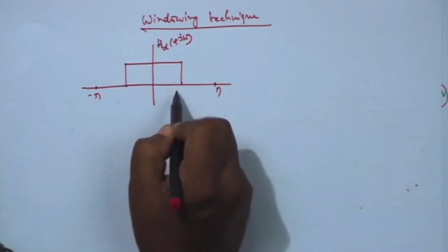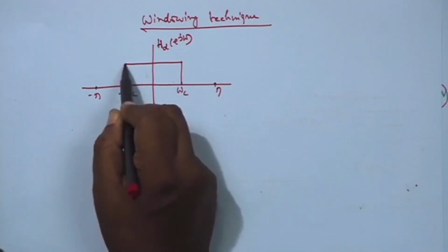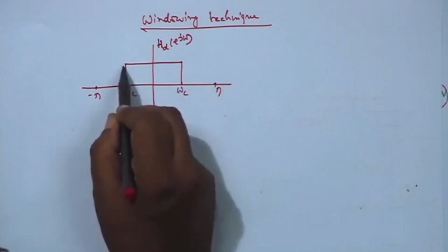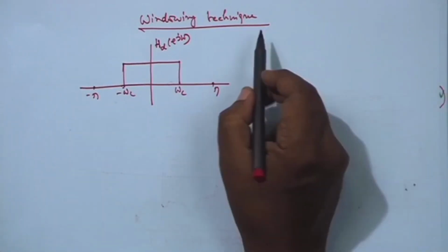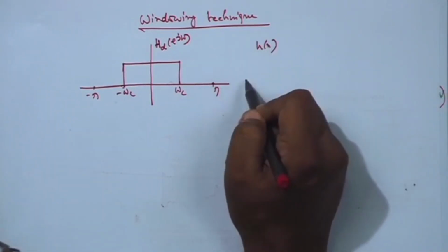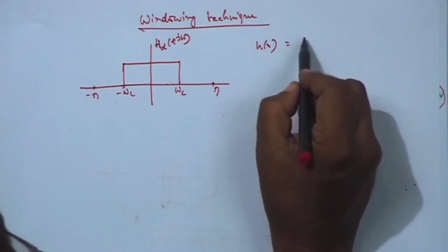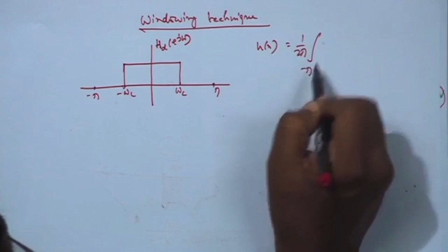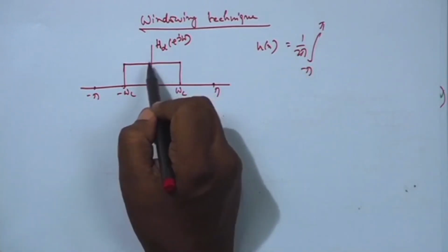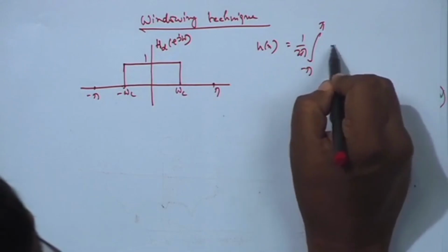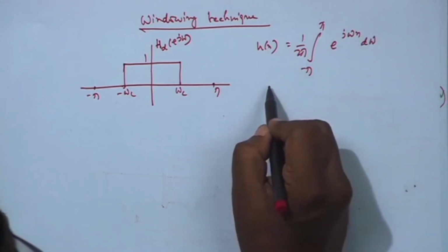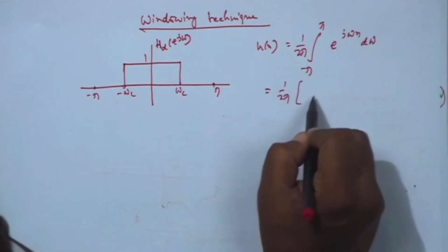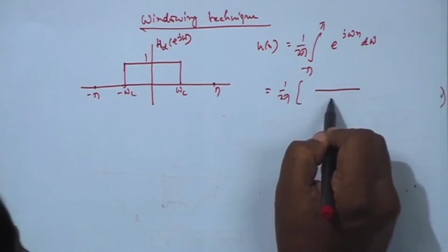I am doing the pass band, it is flat, or outside the pass band it is 0. So, it is abruptly falling to 0 and staying there. Okay. If I really want to find out h n, if I have to take inverse DTFT, suppose its height is 1. So, 1 e to the power j omega n d omega, and if you integrate, it will be what, j n,